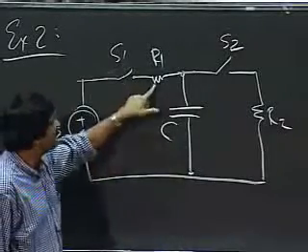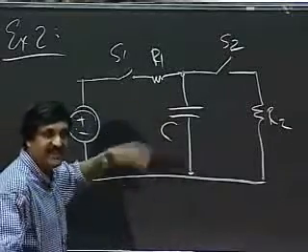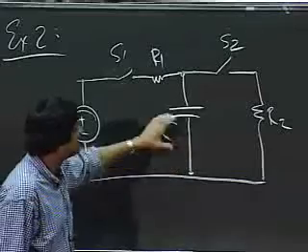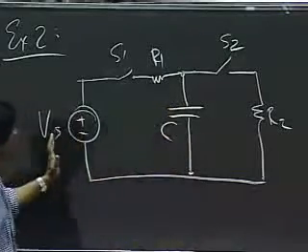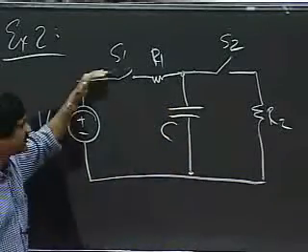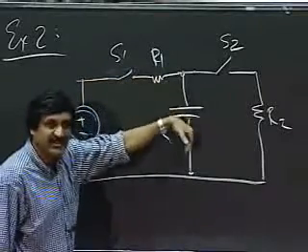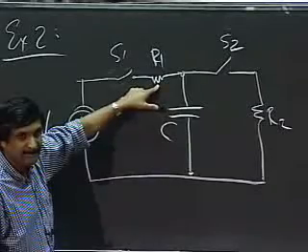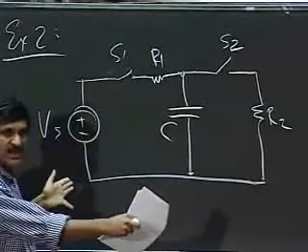And as it's charging up, I have current flow through the resistor, so it's sitting there dissipating power. Notice that this does not dissipate energy, it simply stores energy. So the energy supplied by the voltage source comes in, some of it gets stored in the capacitor, and some of it is being dissipated by the resistor. That gets me to the end of T1.